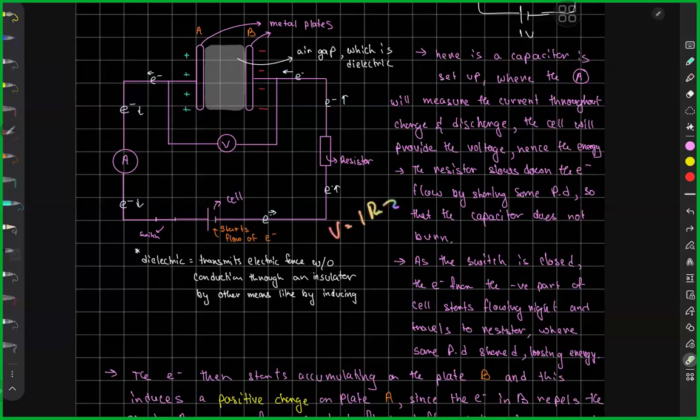And if you agree with me, granted the voltage is fixed, if I vary the resistance in the circuit, I can control how much current flows. If I increase the resistance, what happens? More obstruction for the electrons to flow, less current. And what is the definition of current? Rate of flow of electrons, in essence, right? So if I increase the resistance in the path, I'm decreasing the current. Fair? Hold that thought.